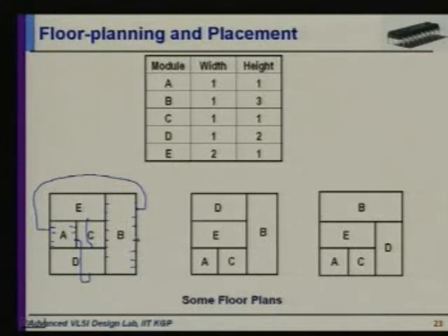There will be a pair of modules which have a lot of interconnections. So it is better to place them close by, so that you are able to route the connections between them easily. If you place them too far apart, then the interconnect is going to eat up a lot of your space. In the design cycle where you actually do this manually, more than 30% of that is spent in planning the interconnection. It's a real big problem.